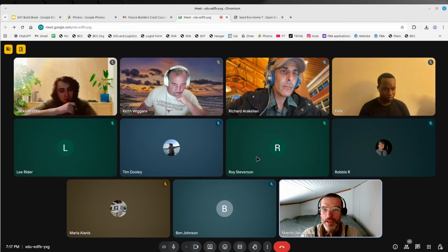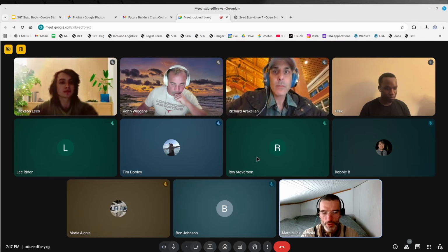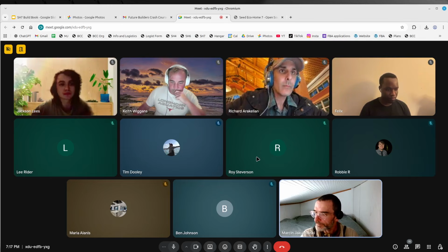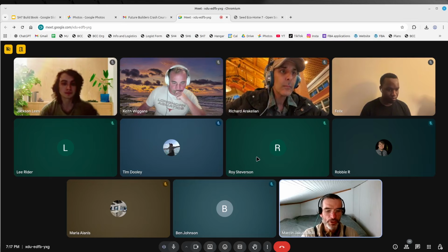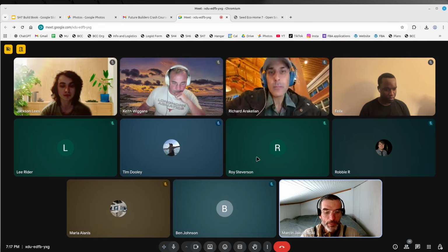Beyond that, I want to show a little update. If you haven't downloaded the latest version, download it if you can right now, or also watch my screen. I want to go through the roof assemblies and describe that a little bit. We talked about walls, which are basically 24-inch on center framing. You've got 2x6 framing. Typically we use oriented strand board. Conceptually, that is very important.